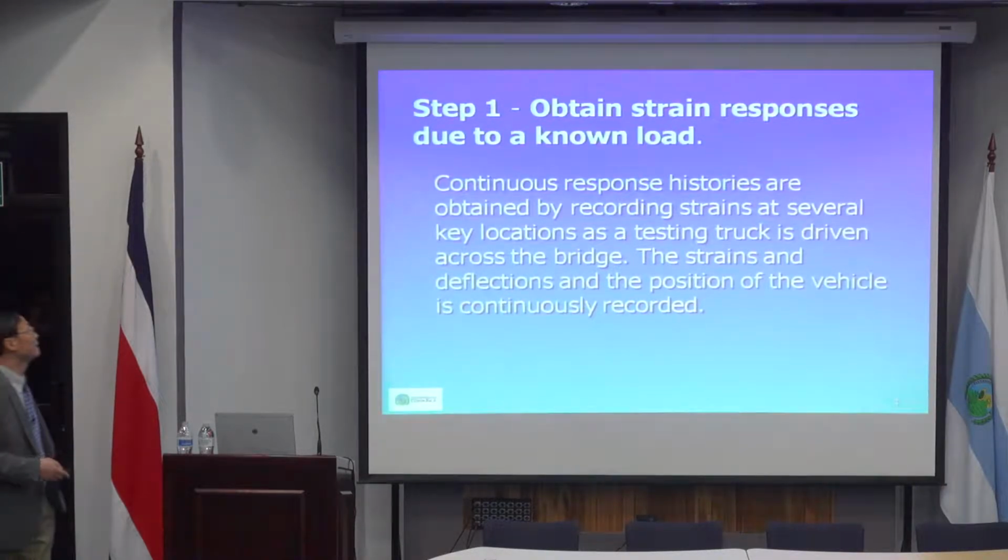So basically, the steps of doing that: the first step is to put a load on and measure the stress. But basically, you cannot measure stress, you measure strains. You can calculate back to stress, or measure strains or deflections. Sometimes you try to measure as many things as you can, because once you compare with the finite element model, you want to have the best fit. The more data you have, the better you can fit.